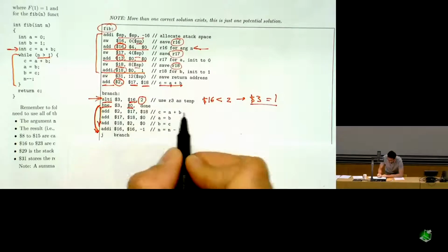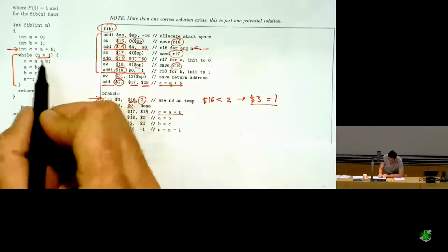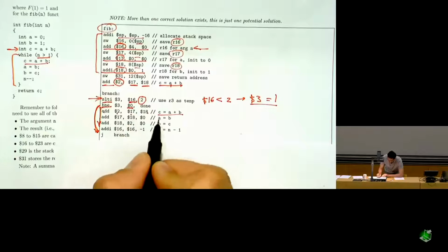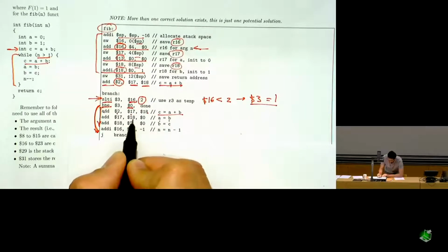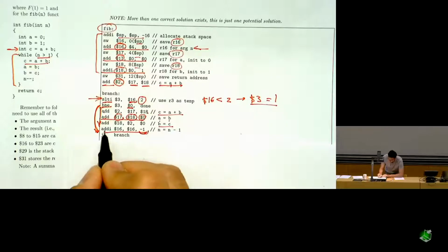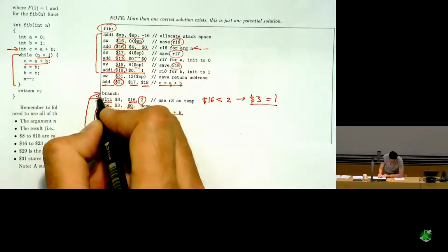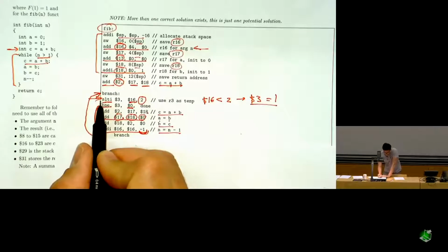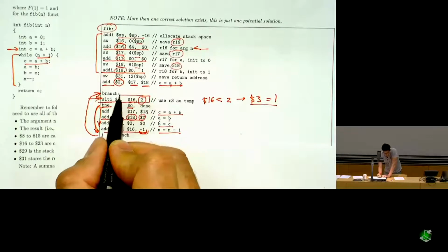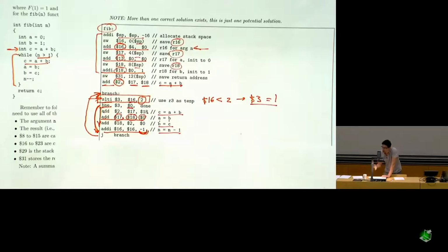And what do we have in the loop body? Well, the first thing that we have is, again, add to 17, 18, that is C equal A plus B, corresponding to this instruction here. Then we store B in A. So what we are essentially doing here is adding B plus 0 and storing it in A, in register 17. We do the same to store C in B, and after that we decrement N. This is an immediate addition of -1 to decrement N. Right after that, we have this unconditional branch, this jump instruction, to start again and evaluate again the content of register 16 that contains N. So we repeat this as many times as needed.